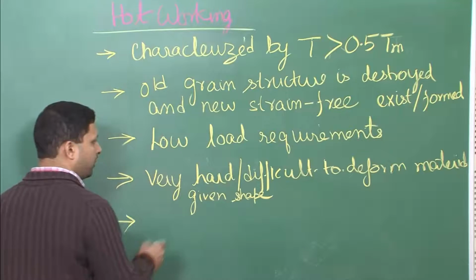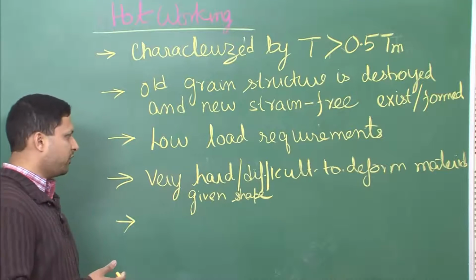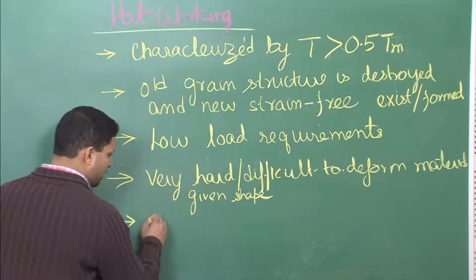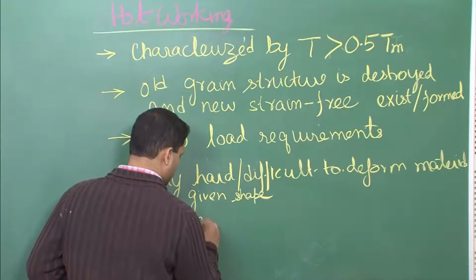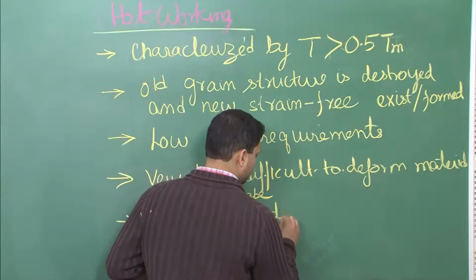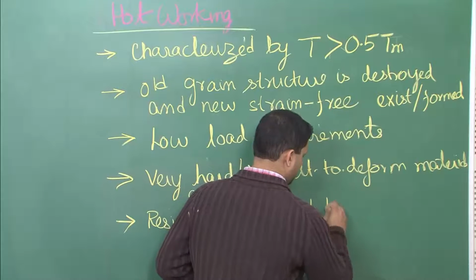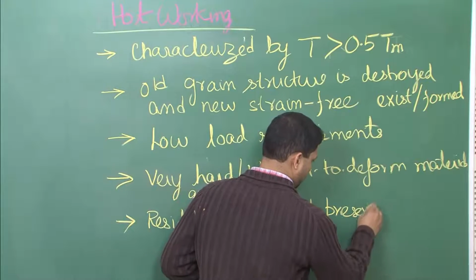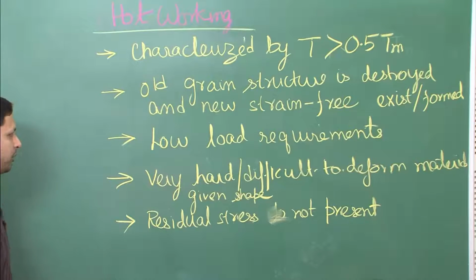And at 0.5, if you remember from the micrograph plot that I drew in the previous lecture, you would know that residual stresses are almost negligible. So, residual stresses are not present when we are working at high temperature.